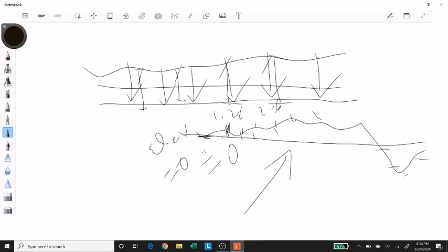So if those mountains are at this much height, there should be a reference, and that reference is usually the mean sea level. So that is where you start from. So in survey as well, we use that reference level. But for executing a localized project, you can introduce your own reference level, and then by using your instrument, you can find out height difference between different points.